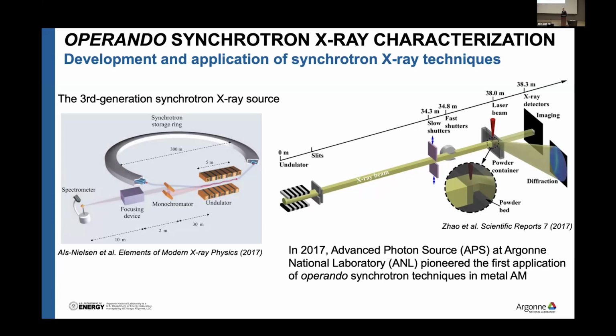It is another mainstream additive manufacturing technique. So you can fire a laser, scan over a piece of metal, and the high-speed X-ray can monitor the entire printing process and offers a transparent view of the melt pool evolution during the printing process, and help us to understand a lot of the highly dynamic physics involved in the printing process.